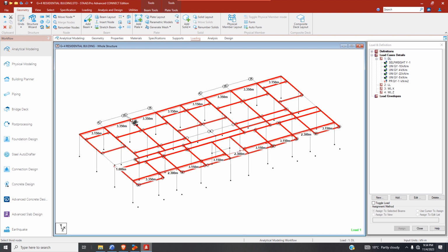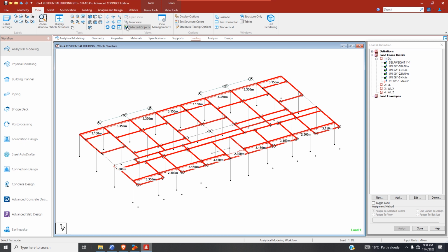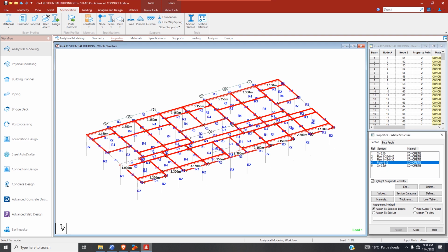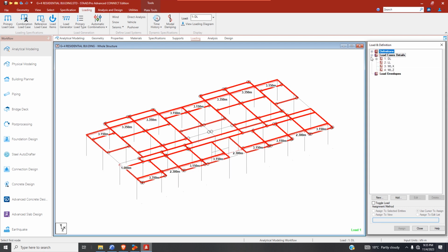Why assign my loads for walls? Because I don't want to do that at each floor. And also for live load, I don't want to do that at each floor. So for the external wall, we just go to geometry. Then select this balcony. I will select the wall pitch. Maybe select parallel to X, parallel to Z. Select all.